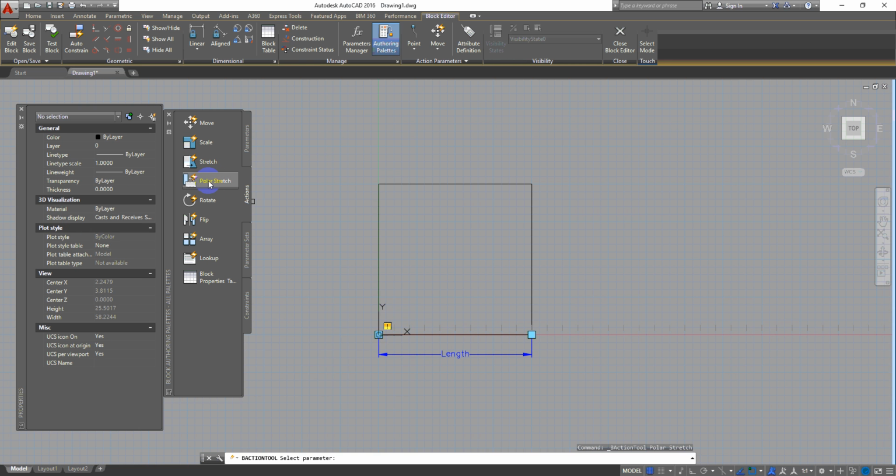If I select this polar stretch and select this parameter, and at this point I want to do the stretch, then select this window, select the objects. After selecting this object, it is again asking me to select object. So what is it asking exactly? Specify objects to rotate only. So I can provide a set of objects to rotate along with this stretch.